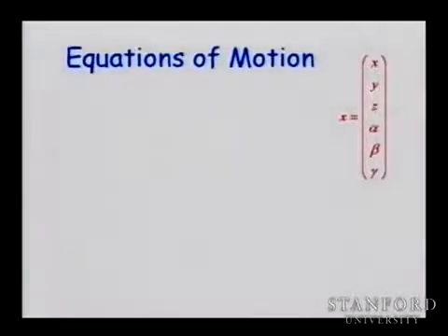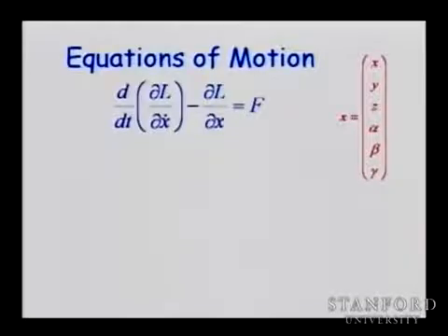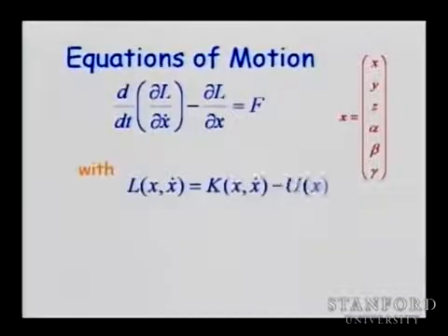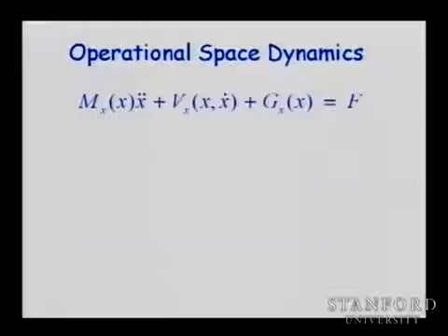So here are your generalized coordinates now. You write your equations of motion with respect to those coordinates. We're taking the partial derivative with respect to x. We're talking about x dot. We're talking about not torques, but forces acting along x, y, z, and the different components. And if you do this computation, you end up with a similar model, an identical model. I mean, I'm changing q to x now. You have a similar model, but now capturing the properties at your end effector.